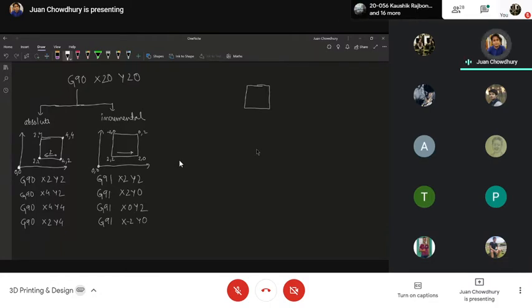I was unable to recall the name yesterday, but I got it. The slicer is creating these 2D slices. If you open the STL file or one slice at a time, you will realize that there is something called a closed loop, and you will find all the coordinates of these points.